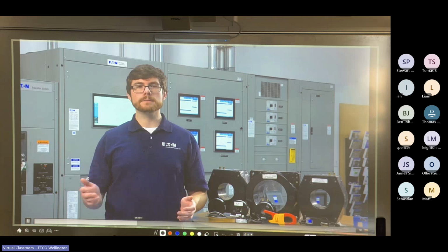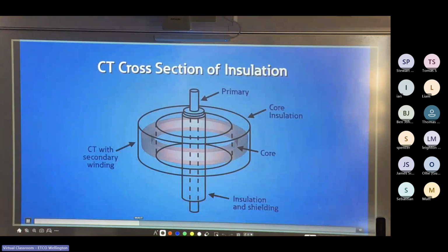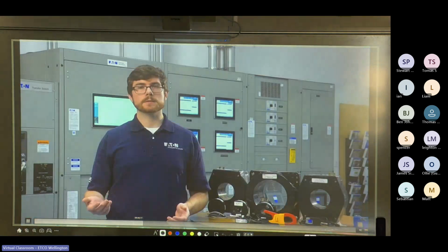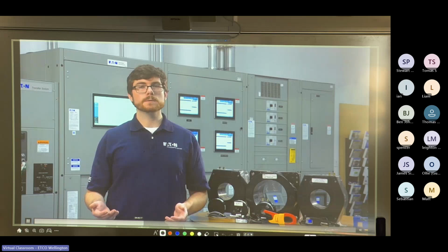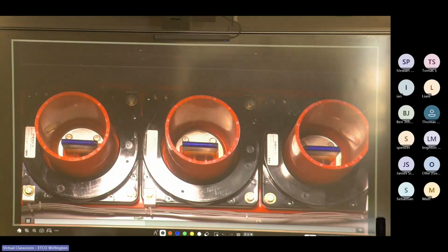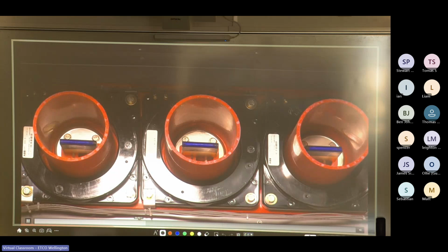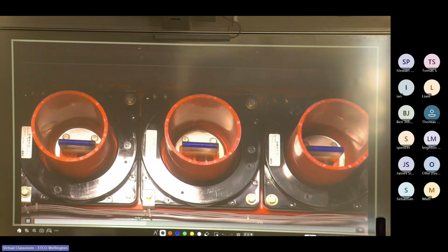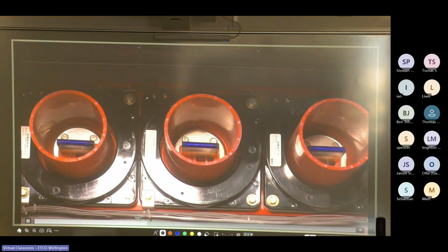In medium voltage, the insulation needs to be rated for the line voltage that the CT is measuring, for example, 13.8 kV. However, this is not the case because the CT is installed around an already insulated and typically shielded conductor. Most CTs' secondary winding insulation is rated at 600 volts. In medium voltage switchgear, the CTs are physically mounted around an insulating material or use physical separation to insulate the CT from the energized bus with an air gap.